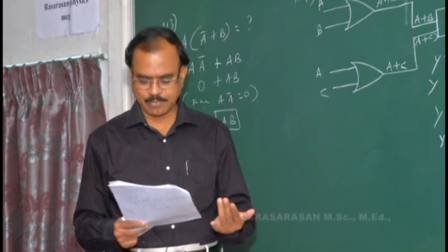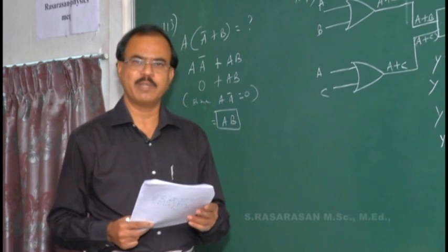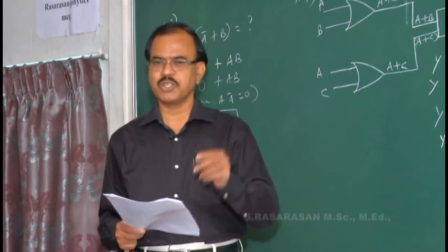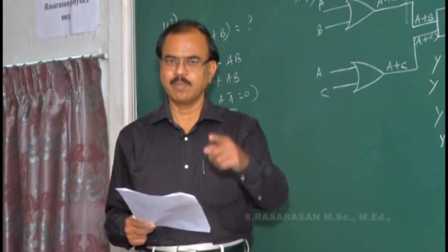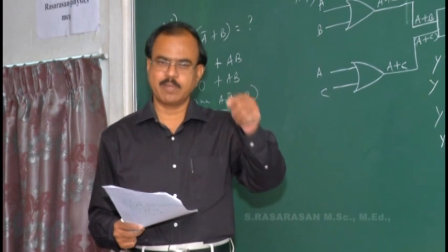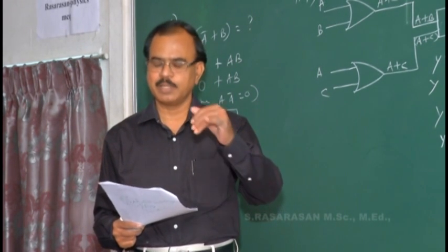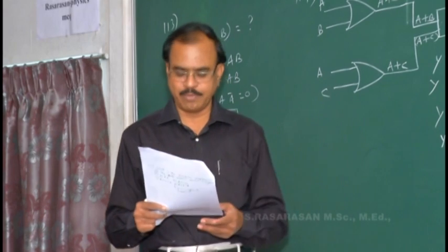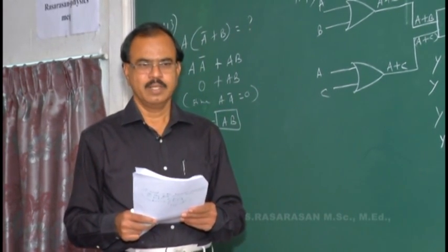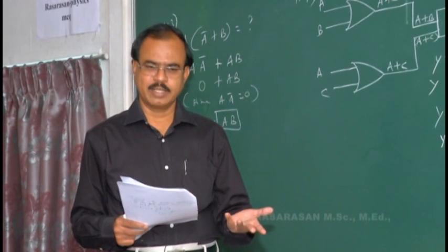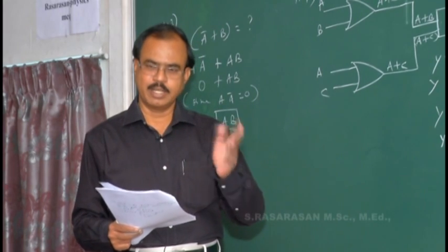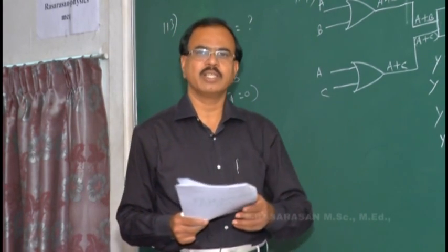The thermoelectric effect and Seebeck effect, these two are the principle of what? Thermopile. Thermopile is a device used to detect thermal radiation, which is based on the principle of the thermoelectric effect, nothing but the Seebeck effect. What is thermionic emission? A tungsten filament is given current and it is heated, that hot filament emits electrons, that is called thermionic emission.